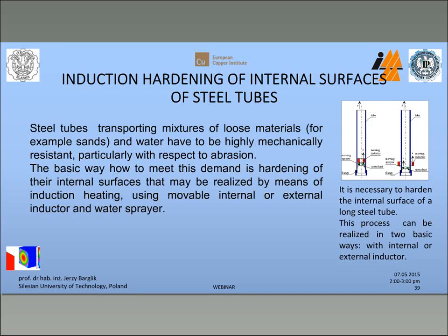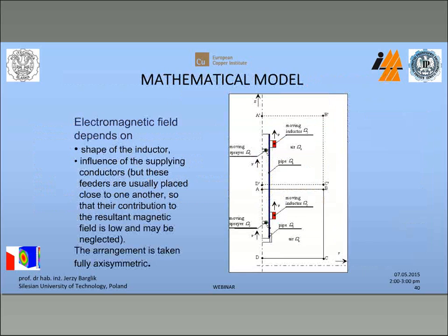And of course, in case of an external inductor, there is a danger that in the region where you weld in order to join tube into tube line, you should reduce the hardness by tempering, and it could be better to use an internal inductor.